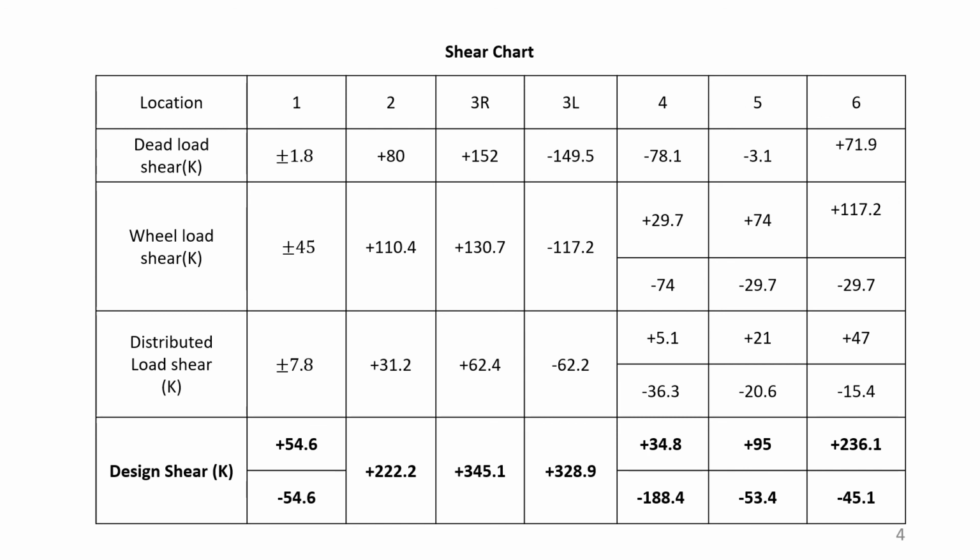Then we will use the maximum numerical values for the stirrup design and shear section design, for the shear consideration, either positive or negative. In moment you will see that if there is positive and negative moment in a particular section, we have to provide top and bottom bars, but in shear we don't have left and right bars. We will use the maximum numerical values for calculating the shear spacing.